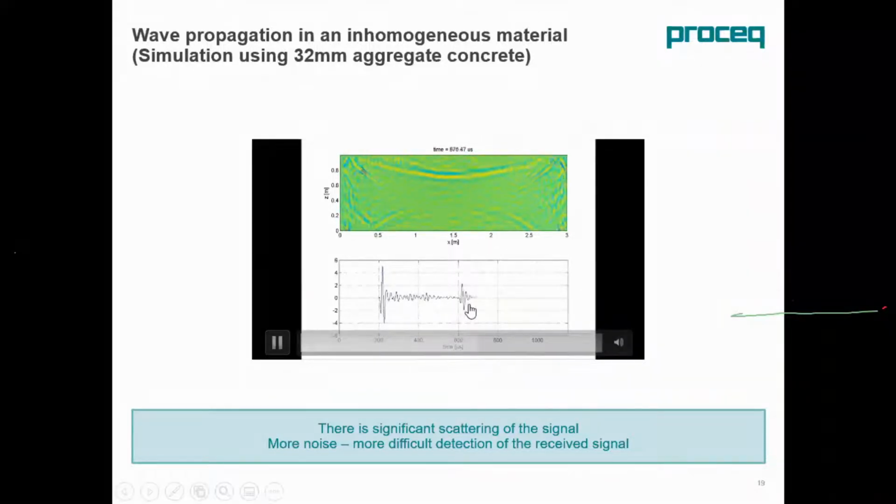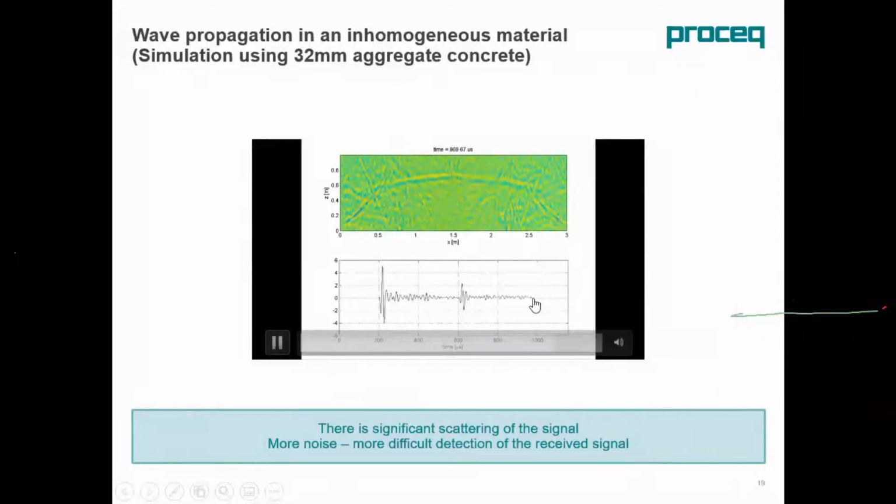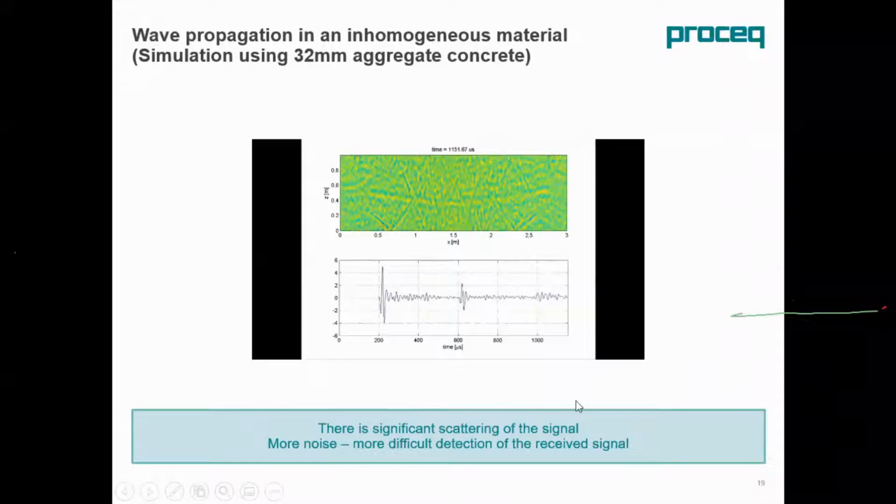It's a bit noisy in the second echo, and by the third echo it dies off, right? So there is a significant scattering of the signal, more noise and more difficult to interpret. So in concrete, with ultrasound we need more analysis to get a good signal.